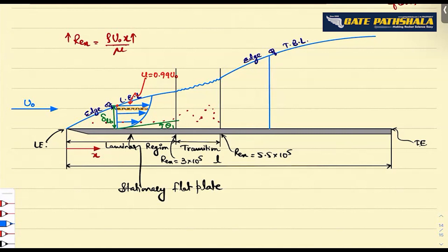So you cannot draw straight lines like you made here for the velocity profile. In this, the paths are completely irregular and the particles will be experiencing huge mass and molecular momentum transfer from one layer to another layer. And the fluid particles move in packets. This is like patches.